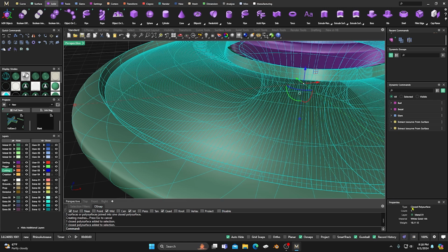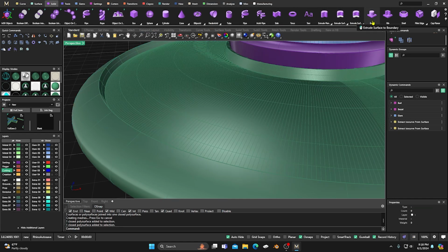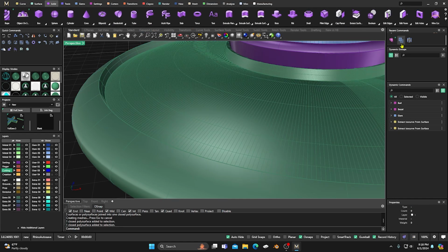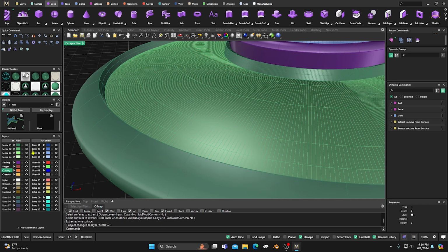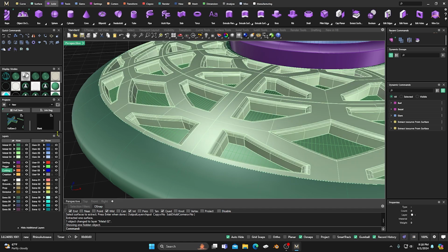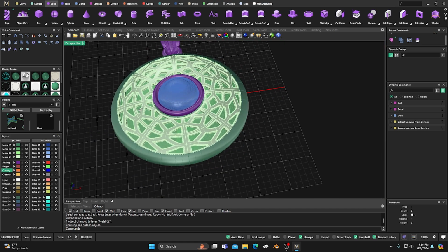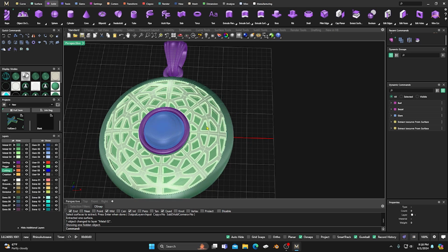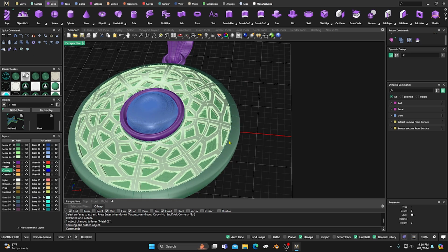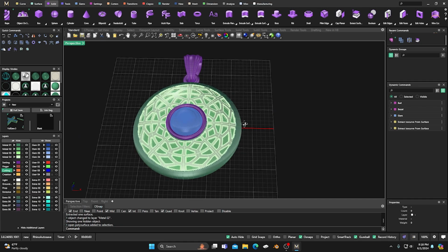And if I take it, look, we got a closed surface. So I'm just going to extract this surface for rendering purposes. Extract surface. It'll be the surface here, and then hit enter. And then we'll change that one to this layer here, right? And then bring back our original cutout there, right? For rendering purposes. But for printing purposes, you'll want to keep that all together, of course, because now this one's an open surface.